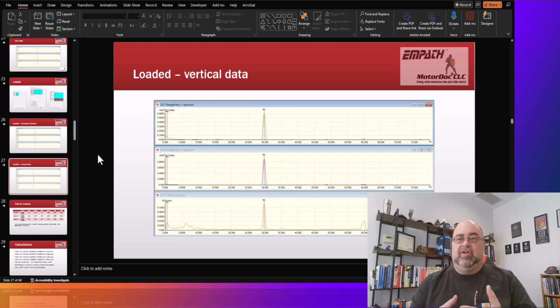So you don't want to do that most of the time, but when you do see something triggered, there are other ways of doing verification. So, we do it in wind. When the cost is that astronomical and you're going to take an asset out, you go in afterwards with a borescope and you verify the test results from vibration or ESA or whatever else. You want to make sure you don't have that 5 or 10% of the time when you've got a false positive.